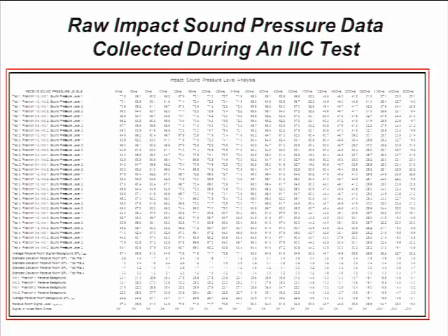Plus, we take another 4 measurements in the lower room for absorption, checks, and normalization, 4 for background noise and 20 for absorption checks and normalization. So that's 60 measurements total at 21 frequencies simultaneously. It adds up to 1,260 points of data for every IIC test we do.